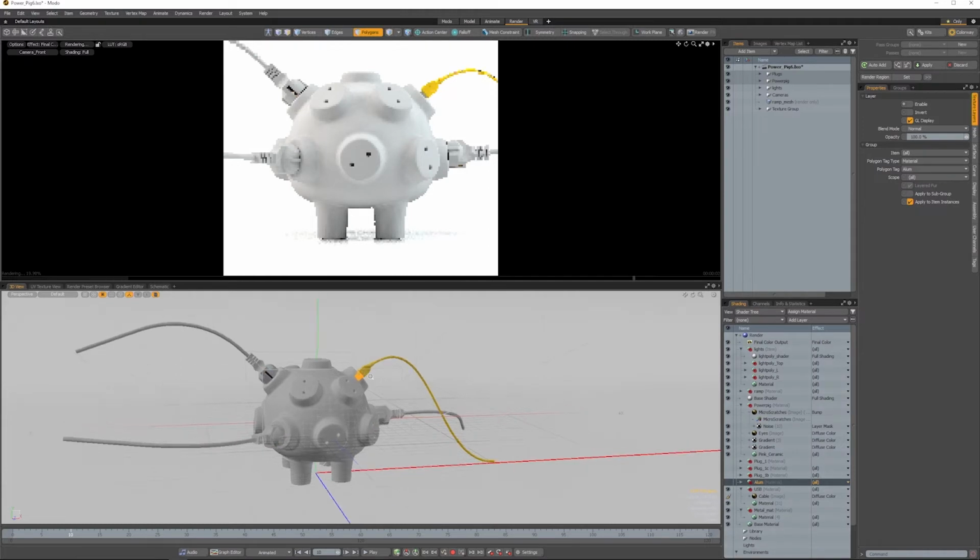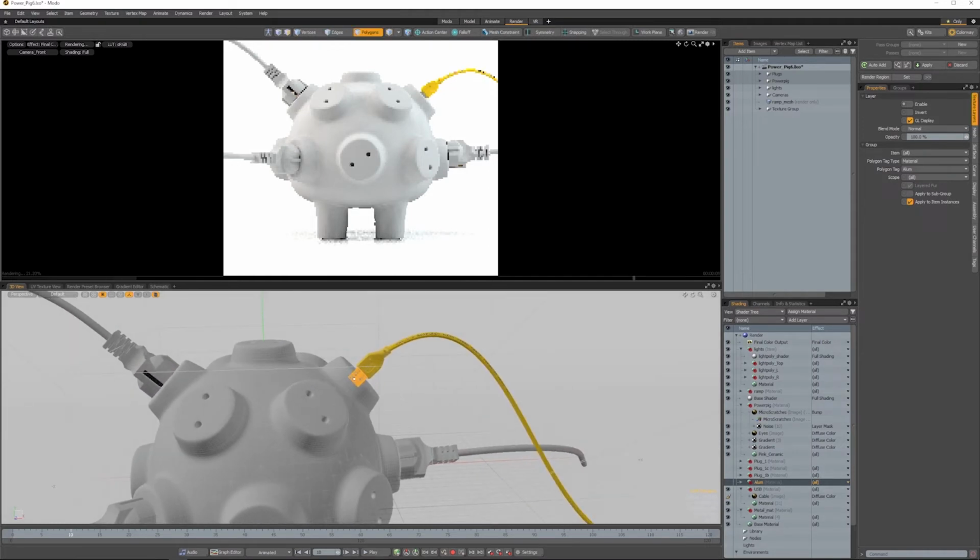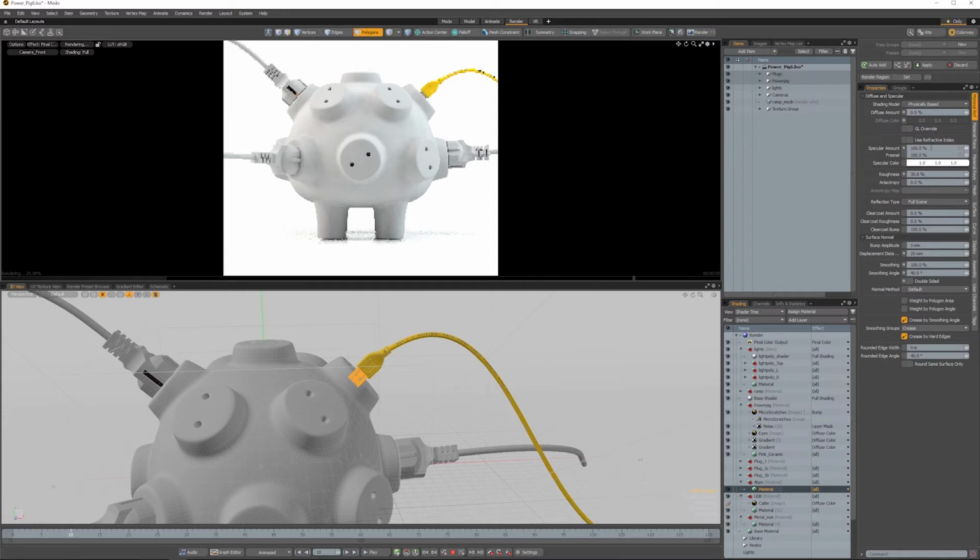Aluminium, so like polygons, those are the metallic aluminium parts of the USB. So again, it is a pretty simple material. Specular 100%, white color, roughness 30%. And you have presets for all these. I just personally prefer to create it myself, it's just faster.